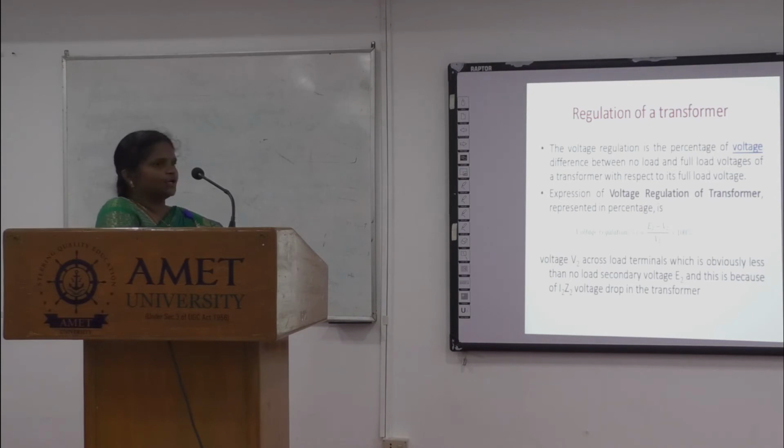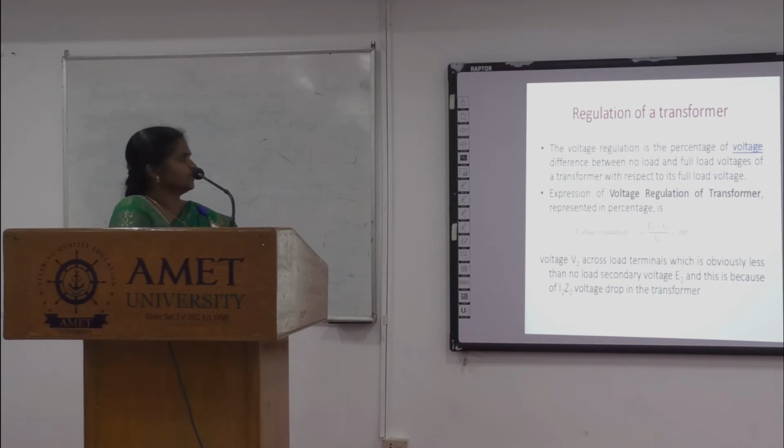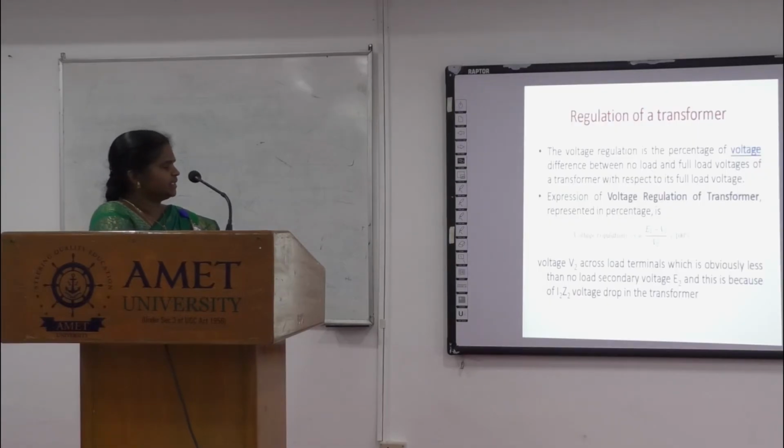The next part is the regulation of the transformer. It is an important characteristic of the transformer. The voltage regulation of a transformer can be defined as the percentage difference in voltages between when the transformer is fully loaded and no load, relative to the full load voltage.